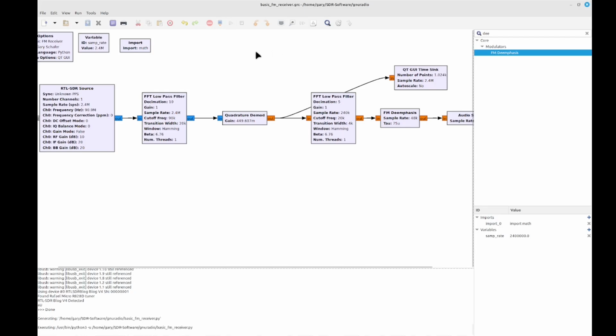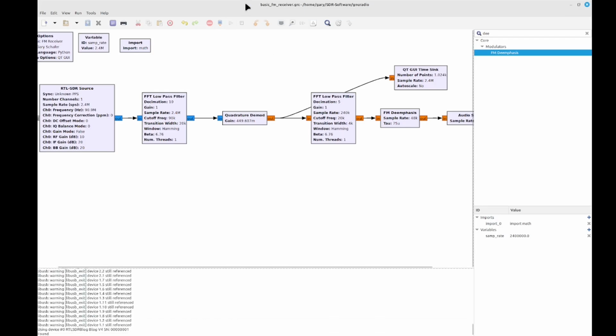And with that, if I play this again, the vigorous string performance of the... And it might be hard to hear, but there's actually now a bit more emphasis on the low. The bass is a little bit stronger because I've now attenuated or reduced the amplitude of the higher frequencies due to this deemphasis. So again, I've now made this whole circuit. And the reason that I added in the deemphasis, normally I wouldn't.